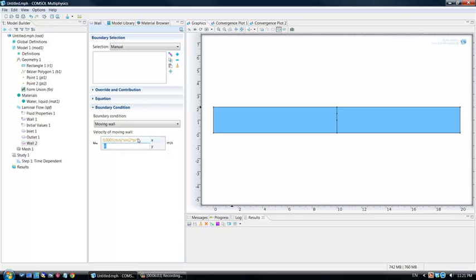And now you see it's in yellow, meaning it's warning me that there's units that are off, or there's potentially something wrong. Now, although the amplitude is correct out here because it matches meters per second, it doesn't like the fact that 2 pi times t, the units will be seconds, but it understands that it needs to be unitless. So I'll give pi the units of 1 over seconds, and so it becomes a unitless function, and it's happy now. Alright, so that now I need to choose my boundary. So I'll choose 3, and I'll choose 8 to have it oscillating.